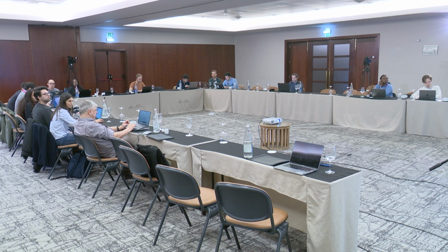If you use a different area, there are a couple of things that need to change. You need to have a global bathymetry, not just a bathymetry of Liguria. You have to use the ECMWF forcings. You have to download the ECMWF forcings yourself. And another thing that you need to adapt is which model you're taking the boundary conditions from. So these are the three things that you will need to adapt if you use a different domain.